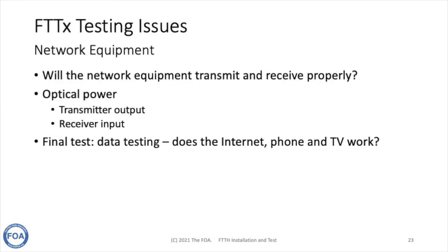FTTH techs may also be involved in testing the network equipment. Will the equipment transmit and receive properly? And troubleshooting or testing is very simple. It's a matter of optical power, like every other network. Is the transmitter output within spec? Is the receiver input within spec? And then, of course, if it is, you plug the system in and see if it works. Fortunately, it's pretty simple because of all the diagnostics that the manufacturers have built into the equipment itself.